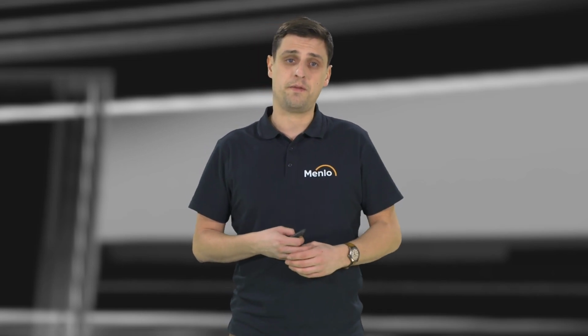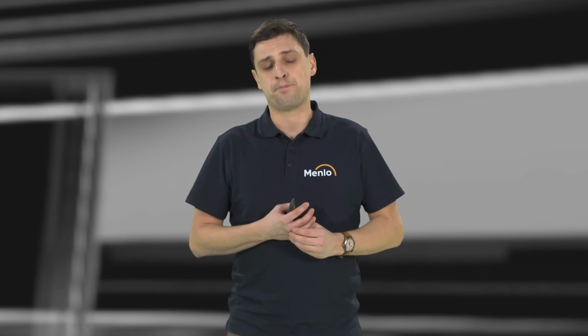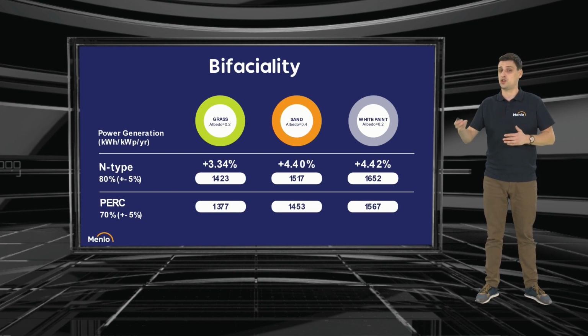And it's worth mentioning also the better bifaciality factor, which leads us to better production when we use bifacial models and when we use the bifacial effect. Depending on the surface below the model, the increased production is 3 up to even 4.5% additionally.